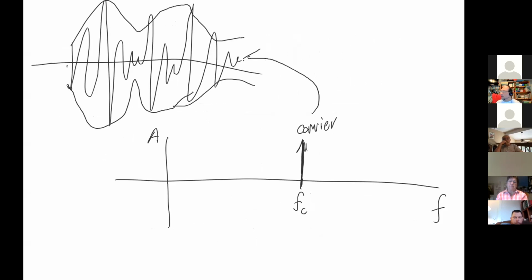Which again, is that high frequency signal inside. And then we're going to end up with these modulating pictures. This is a frequency representation of the voice that's making the thing get bigger and smaller. These are known as sidebands. So we have, since this is zero frequency and this is infinite frequency, this would be the lower sideband, and this would be known as the upper sideband.